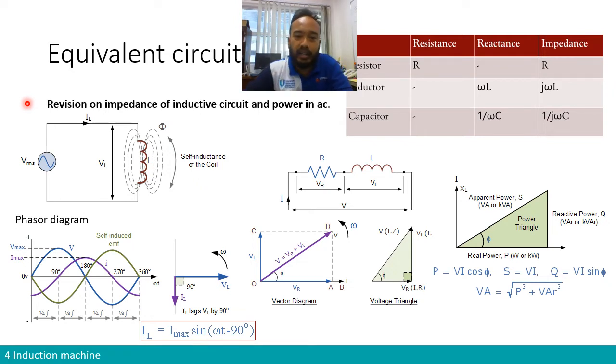So what is impedance? Impedance is basically the combination of resistance and reactance, right? Resistance and reactance. It is something that you have seen in basic electrical principles in first or second year. So Ohm's law applies not only to a resistor, but also to the impedance. For example, if you have only a resistor, then your circuit will have only resistance in terms of impedance. But if your circuit has an inductor with a certain reactance, that modifies the relationship. Well, not the Ohm law itself, but the relationship.